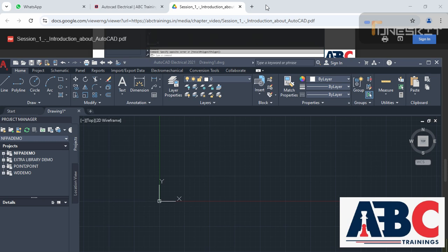Let me see the coordinate systems of the workspace. X and Y are the coordinates of the workspace. There are two coordinate systems in AutoCAD: the world coordinate system WCS and the user coordinate system UCS, which define the angle of the XY plane you are working in. Objects in a drawing are defined by the coordinates necessary to draw them. Coordinates are simply the numbers for each X and Y, and the position Z, that define the objects.